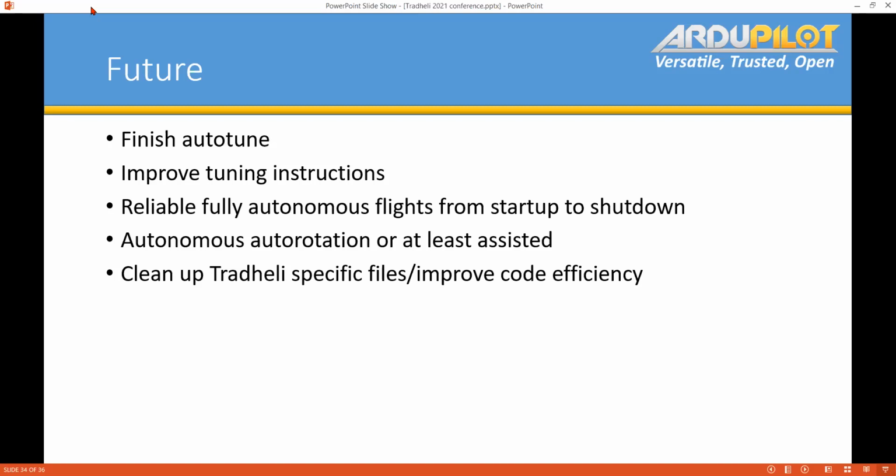I mean, the big thing is controlling vibrations is one of the huge things, and trying to find a good spot on the heli where you're going to get low vibrations, either due to frame or the mounting. Yeah, and also making sure that all 6 degrees of freedom on that isolation mount don't coincide with a rotor fundamental or the right harmonic. You don't want to, yeah, exactly.